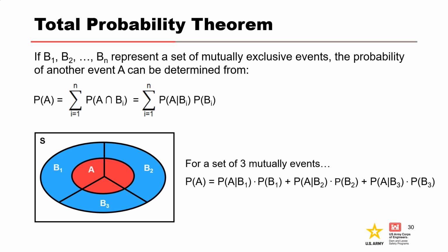through an event tree to calculate the annual probability of failure. The probability of a given load is multiplied by the probability of failure given that load. This is done for all loading conditions, and then those products are summed to get the total probability of failure.